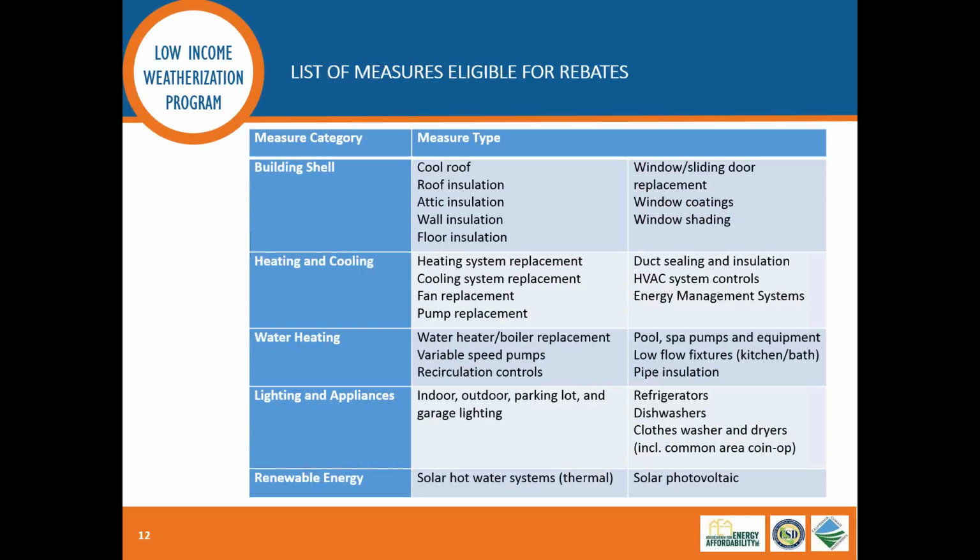It encompasses really many different facets of the building. And similar to many other weatherization programs, there are a lot of opportunities in the building shell as a starting point. We can look at insulation in the roof, the wall, the attic, possibly also insulation under the roof if you're considering a roof replacement. We also can look at cool roof coatings or cool roof tiles.